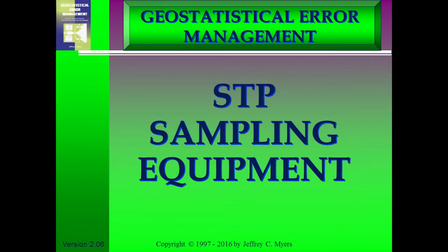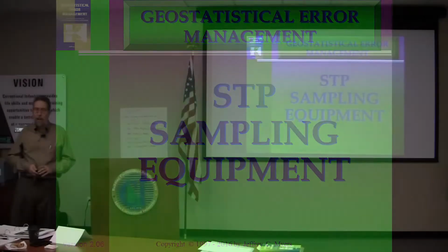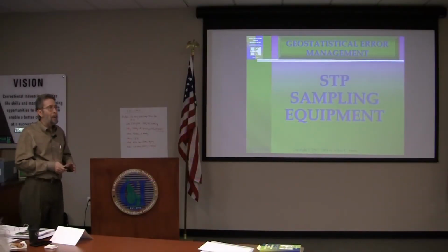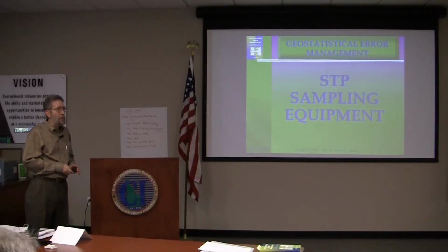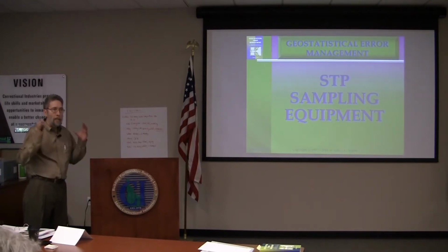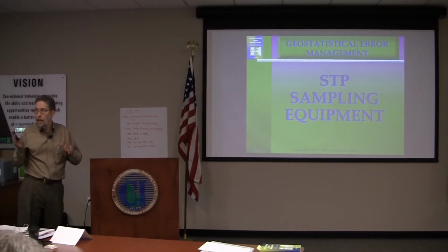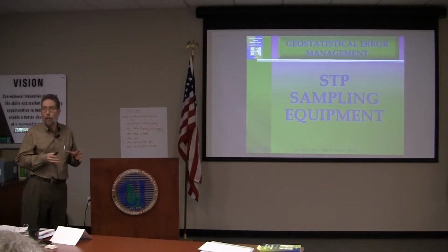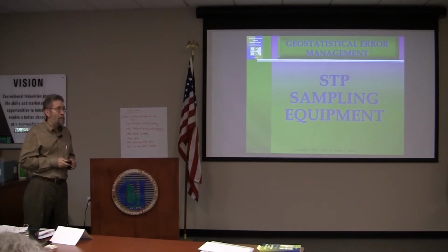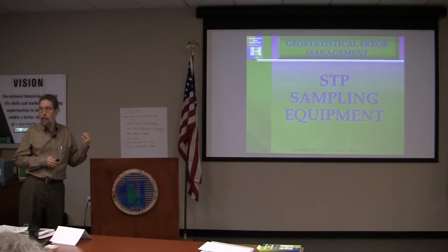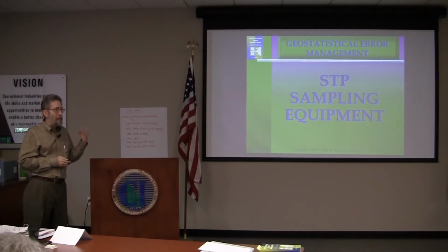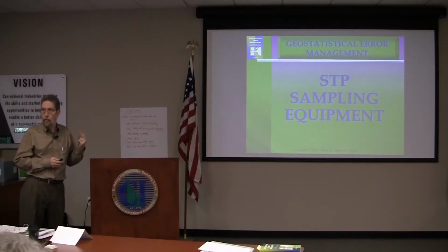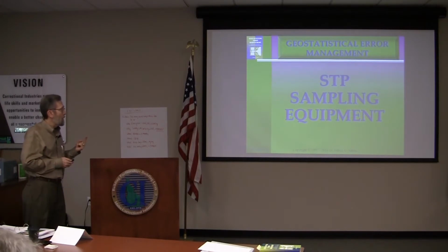This is a follow-up to the heterogeneity talk. The heterogeneity is our starting point for sampling and decision making, but even once we conceptualize what the heterogeneity is, there's actually a big issue about extracting the material correctly, because we can also mess up the sample at that point. You remember in Pierre Gy's error diagram, the 7 sampling errors, there's increment or sample delineation error and extraction error. So they're 2 separate errors. We'll talk a lot about that here.